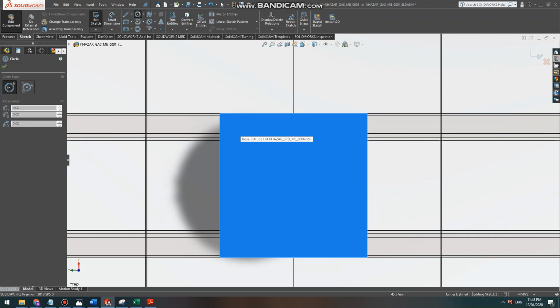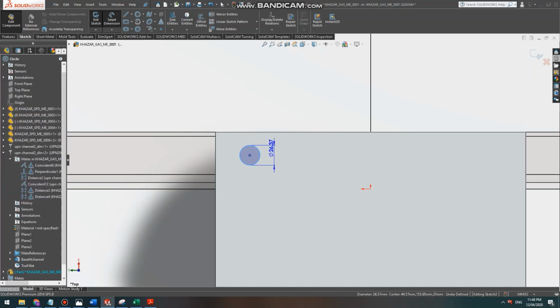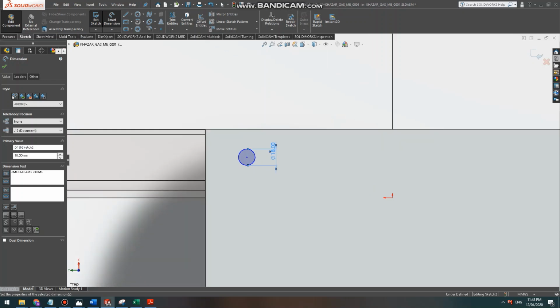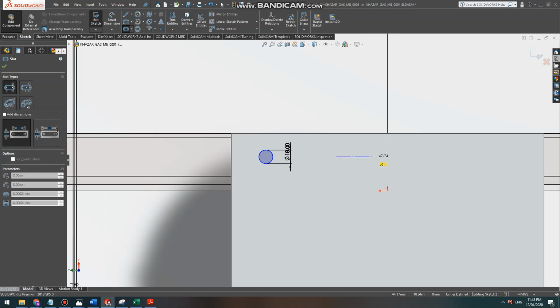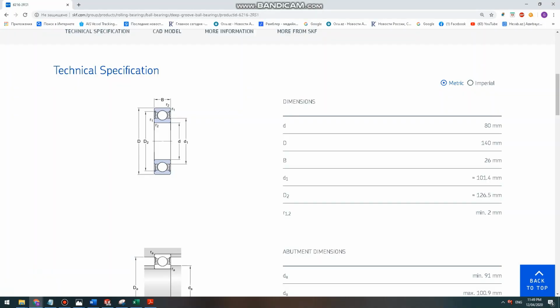And as you know, if you're using bolt M16, your hole has to be at least 18 millimeters. So you give 2 millimeters of tolerance for the production side in order to be able to mount it. There are even some cases where they make slotted holes like this, so it's much easier to mount. It eases the production procedure. Of course, there are some projects where we have to use 16 or 17 millimeter holes. It's a close fit, so there are types of fits.